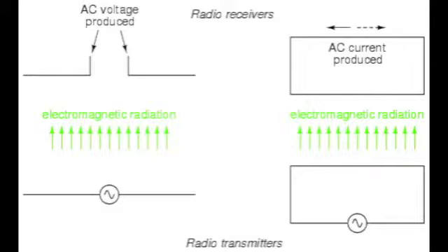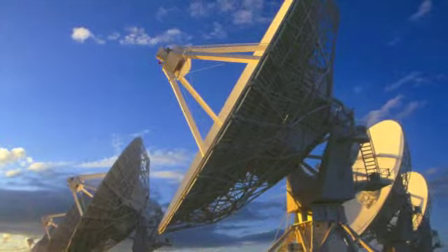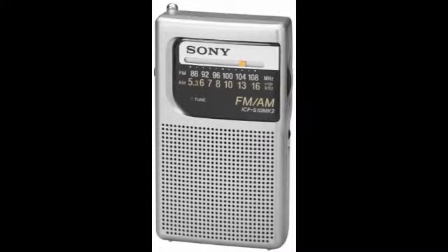As their name implies, AM radio modulates the amplitude of a signal to transmit info, whereas FM radio modulates the frequency of a signal to transmit info. The two bands cover from 500 to 1700 kilohertz for AM and 88 to 108 megahertz for FM.